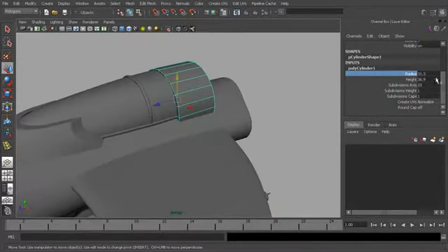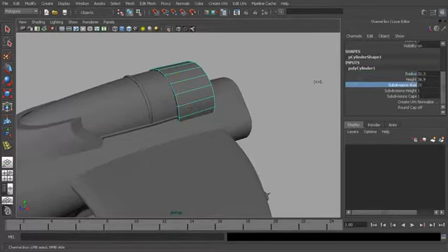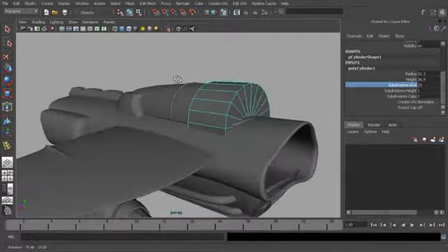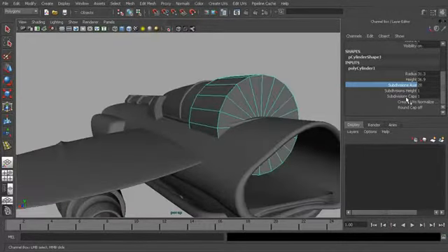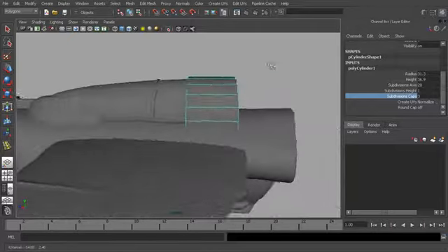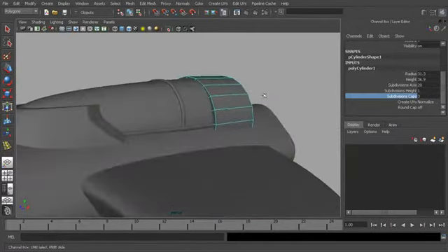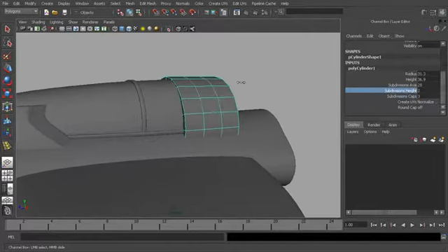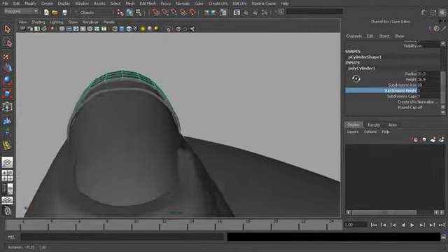All right, now the subdivisions you can change if you wanted to make those higher or lower. You could do that. I'll go ahead and leave those as is. Now I do want to create some subdivisions on the caps. Right now we don't have any of those, so I'm going to create a couple of subdivisions there. And then I also want to create some subdivisions along the height. So we'll create 2, basically.